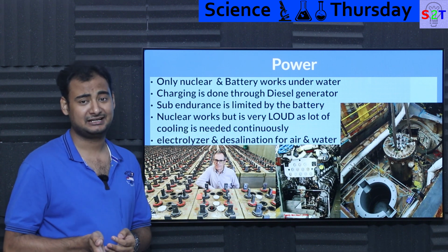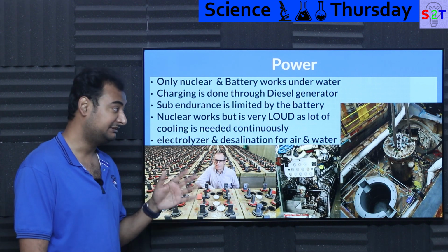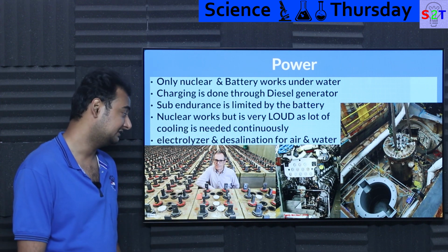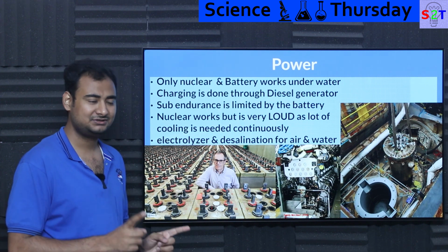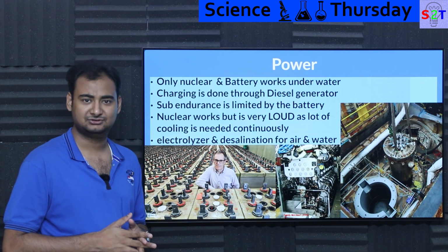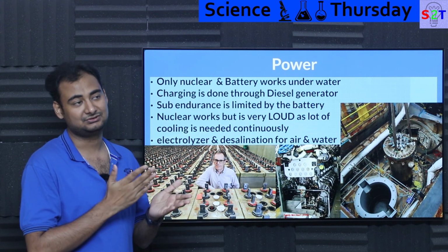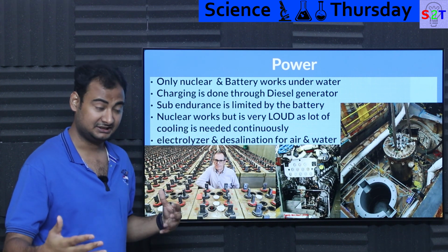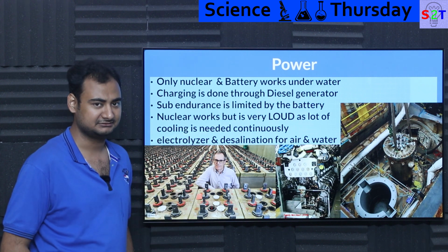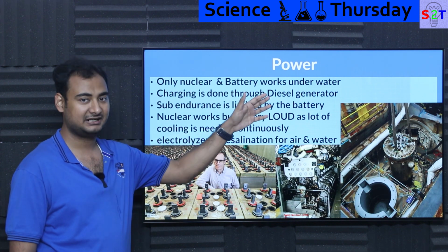The most advanced thing I have heard, because be mindful, at this point in time, if you look at any US submarine that is not nuclear powered, even nuclear powered ones will have battery backups. They are generally lead acid batteries. Why the hell is nobody using lithium ion? Well, there is one Japanese submarine that's supposed to be using lithium ion, and I'm reasonably sure they must be using lithium titanate batteries, because again, I do not like the idea of putting flammable things in an enclosed space. So it does make sense to use lithium titanate. It has a longer lifespan, and these equipments are idiotically expensive. So enduring lifespan is something I think they will value, and it's low quantity enough that they should be able to afford it. So nuclear and battery, that's the only option.